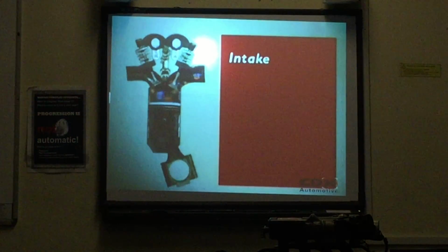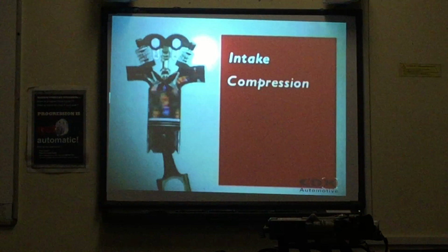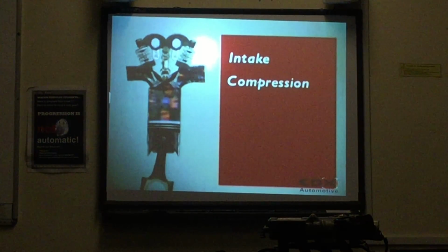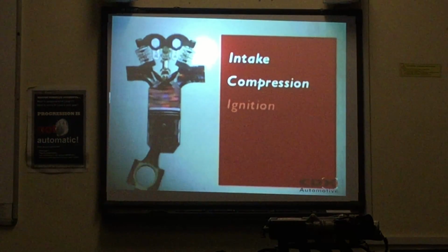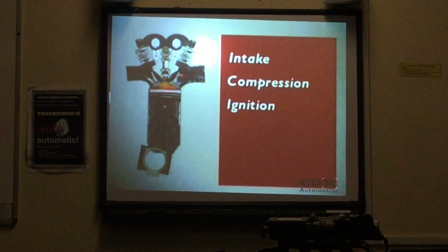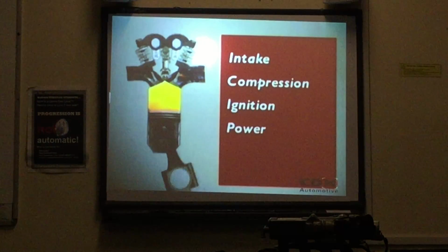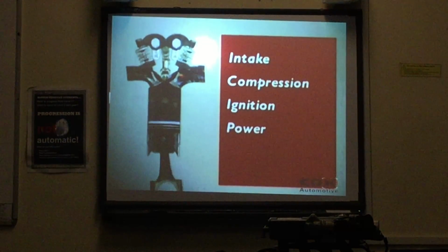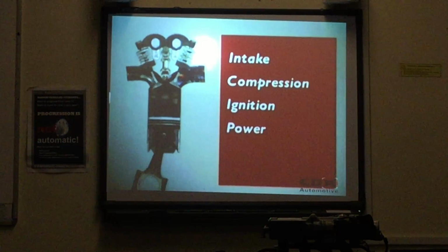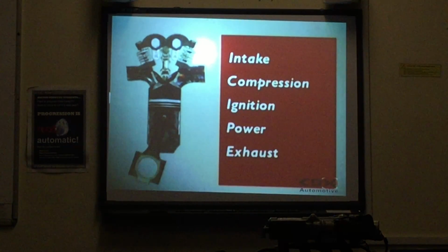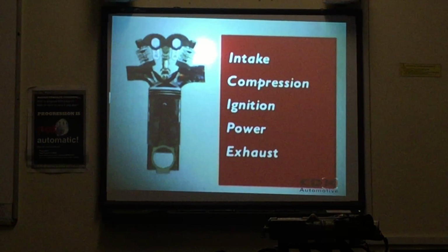Let's look at the cycle operating. Intake takes in air-fuel mixture. Compression squeezes the air-fuel mixture into a smaller and smaller volume. Ignition, the mixture under pressure is burned. Power, burning expanding gases push the piston down, creating a power stroke that turns the crankshaft. Exhaust, the piston moves upward, forcing burned gases from the chamber. All 5 events occur in this order in each of the engine cylinders.